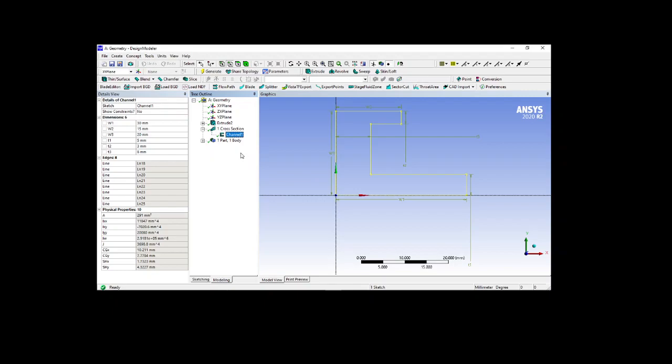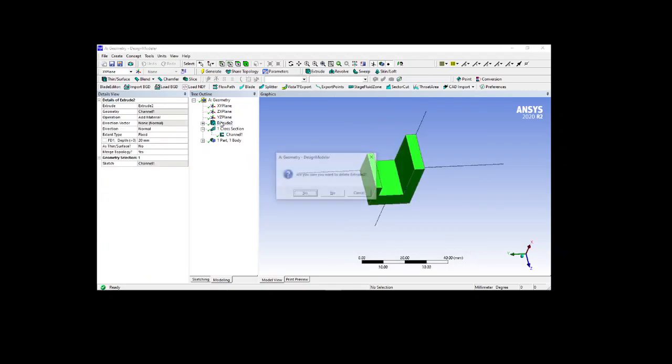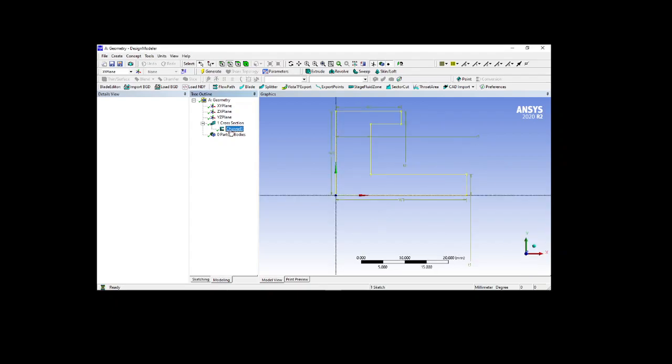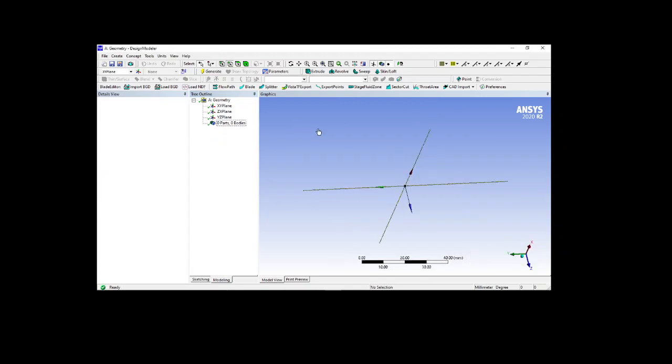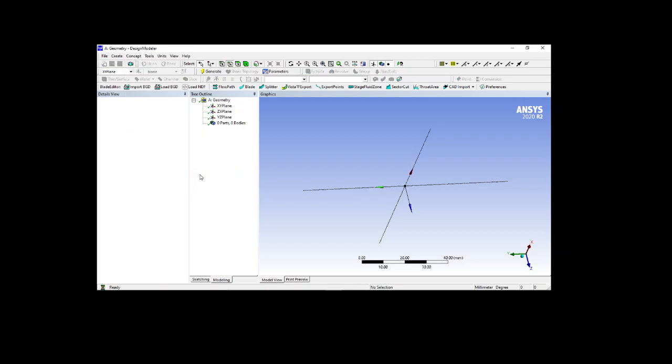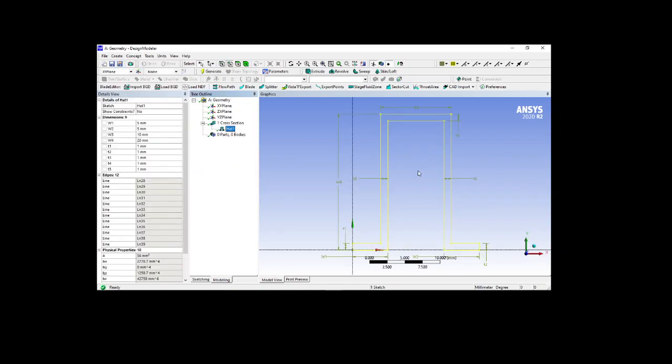Okay, so now this is the normal section. I will delete the first extrusion. This is the sequence in which we created the geometry. In exactly the opposite way we have to delete the geometries, because the definition has been derived from the previous geometries. Now we will go to the concept toolbar. Here the Z section is there, the L section is also there, inverted T sections are there, and I will go for the hat sections. The hat section is already available here.